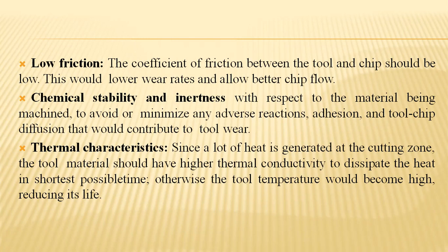Coming to the point of chemical stability and inertness, adverse reactions or adhesions are avoided or minimized, because tool-chip diffusion contributes to tool wear. So the characteristic of chemical stability applies particularly with respect to the material.